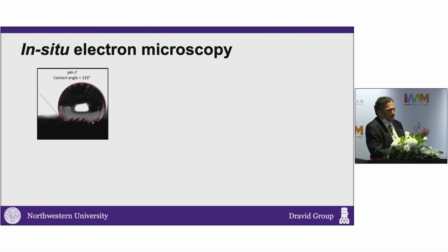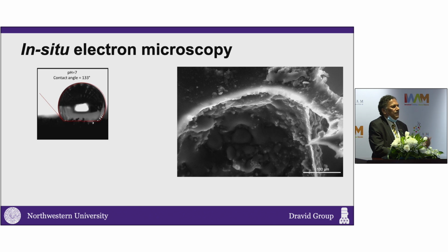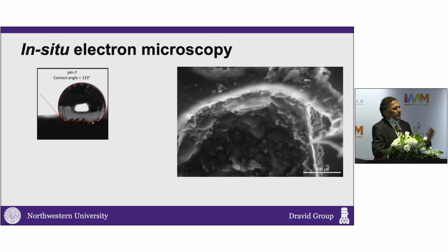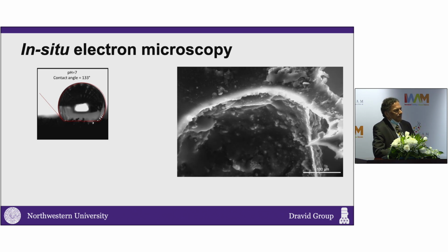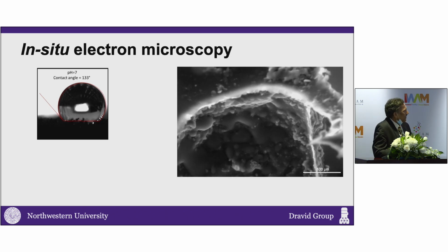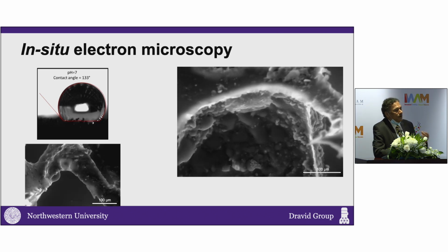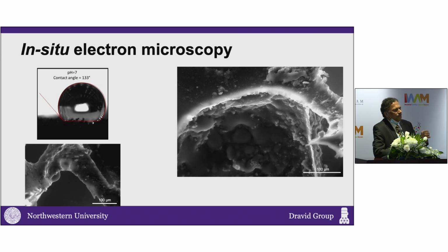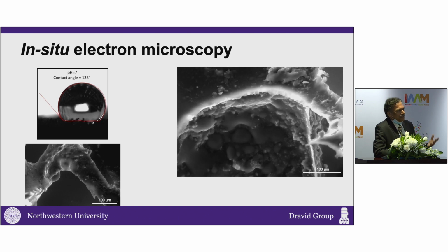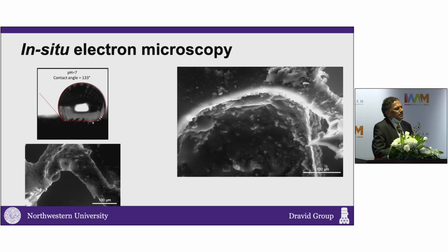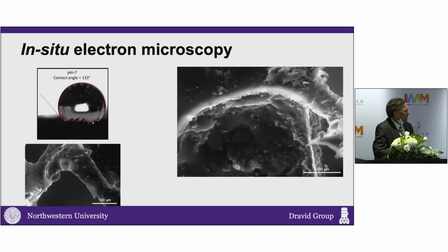So just a quick couple of slides to show how this goes. We can do typical studies of wetting angle measurement, but also do it in situ while we introduce a water-oil mixture in an electron microscope. These are called environmental SEM, very classic ones. So we introduce water and oil and other relatively high vapor pressure products, and you can watch the microstructure evolve in interaction of the fluid with surfaces. And you glean a lot of insight as to what is the role of curvature, what is the role of asperities, because it's a very complex undertaking. You have sharpness of edges and corners in the sponge, you have surfaces, you have different length scales involved, you have capillary effects. So it's a very dynamic system, and it works remarkably well despite all these challenges.